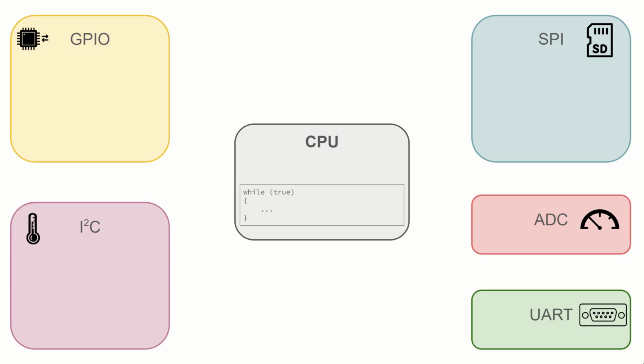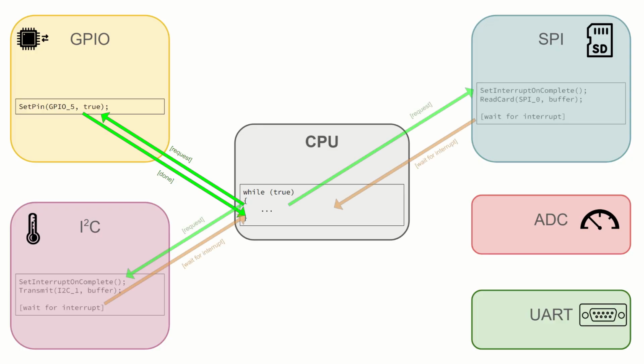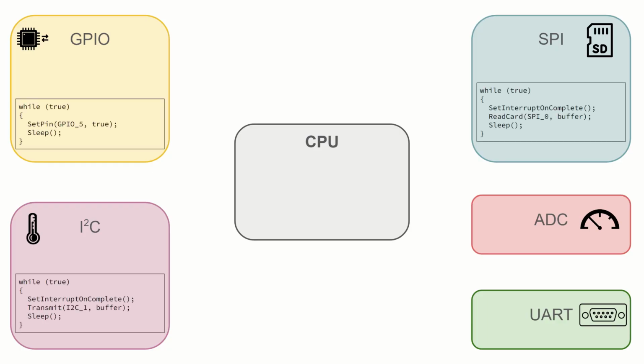Usually there is an infinite loop in the program where we handle all the devices and protocols. It may be simple if all we have to do is to change a state of some GPIO pins, which is instant, and we can then switch over and handle another device momentarily, but often the tasks we perform may take some time. Then we usually use interrupts to carry on when the task is finished. In such cases, we need to switch to another piece of code to do some other work, which quickly gets messy as you need to remember where you were to be able to carry on when finally the long-running communication raises the interrupt. It would be much simpler if we could handle each device logically in one place, one function,